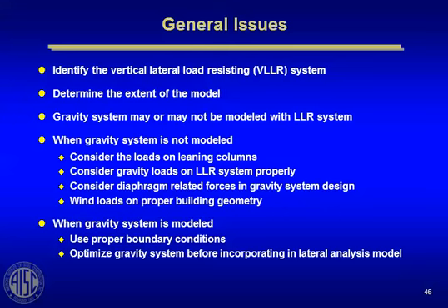You're going to put a big torque on the building, and that's undesirable from a seismic standpoint in earthquakes, certainly undesirable from a wind standpoint, because it may cause your building to just go into a torsional oscillation. So proper location of the lateral load resisting system early in the project is a key element to a successful design.